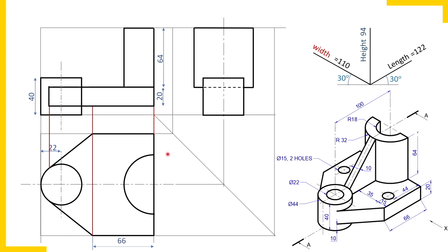Okay. Now this shape has sharp corners here. Watch here, this corner. And the corner is formed by three edges. So clearly in our isometric view, that is this pictorial or three-dimensional view, you can see this edge which is vertical, parallel to height. So from this corner, draw the projector and draw the edge. So this plate we have completed here.